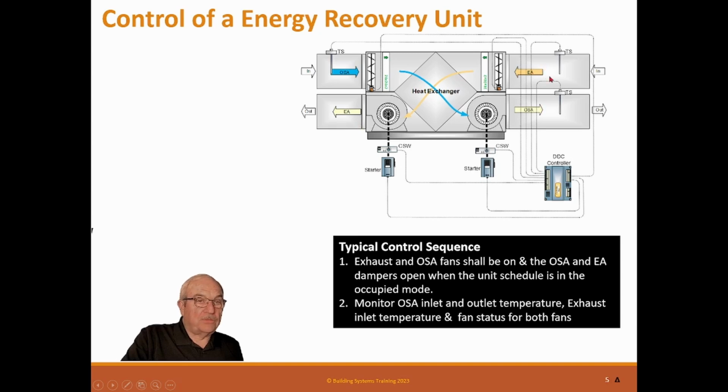So these temperature sensors, if you take this sensor and that sensor, you can see the total amount of work that your unit has done. This sensor is good to know just what our new temperature is from the return temperature, but basically these are the two that tell how much energy you have recovered.